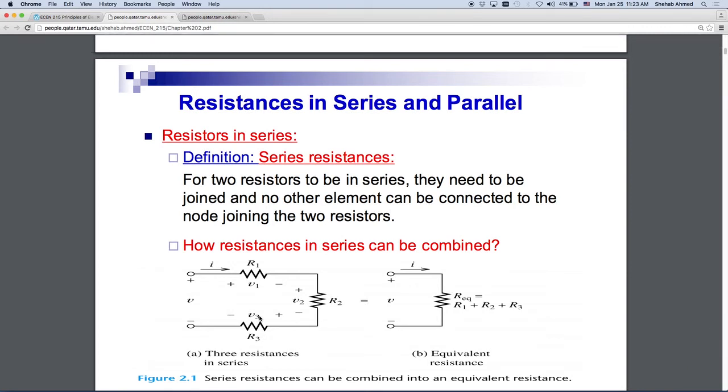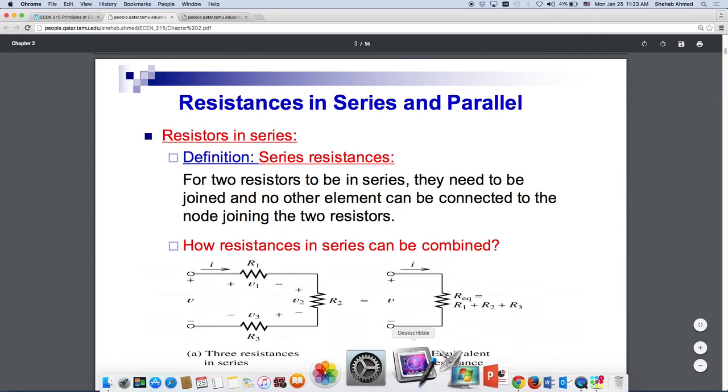How about if they're in parallel? You have a pipe and you have 3 outlets in parallel. Do you think that will increase? Each of these requires a certain flow rate. So you have 3 loads, each requiring a certain flow rate, and all of these are in parallel. What will the total be? Definitely a higher flow rate than each individual flow rate. So basically you add each individual flow rate if they're in parallel, right?